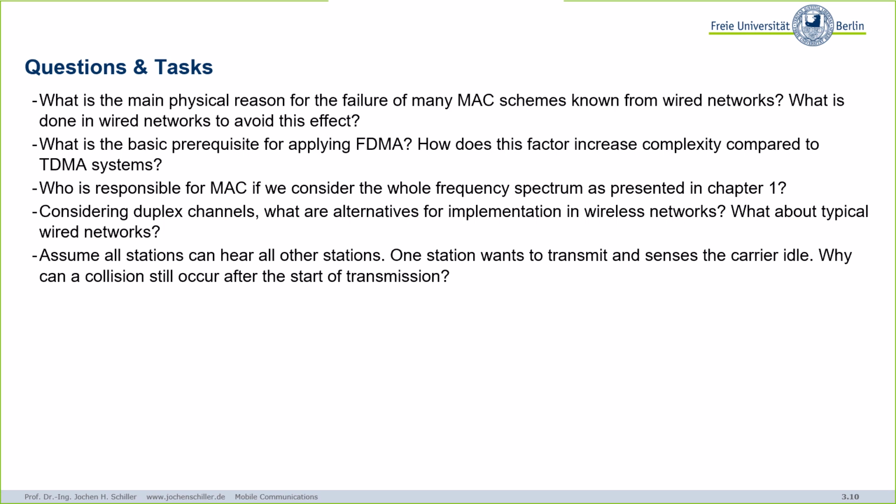But in theory, and in wired systems and for audio, you can do exactly what you wrote. You can send and receive on the same frequency at the same time, because you know what you send. And if you know the echoes, you can subtract the echoes and your own signal, and you will have the original signal. This works if your signal and received signals have roughly the same strength. Well, maybe by the order of 10 weaker or something like this, but not a factor of 1,000,000 or 1,000,000,000 weaker. And that's the problem in wireless systems. This is why we cannot do it.